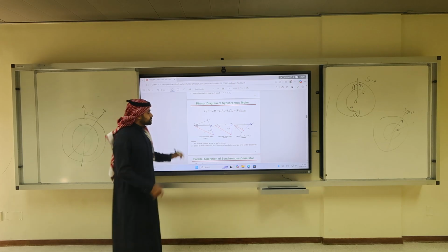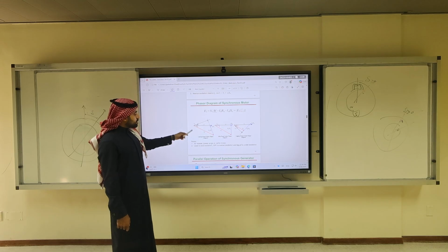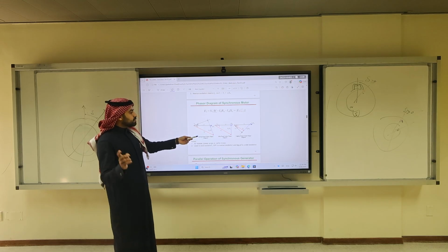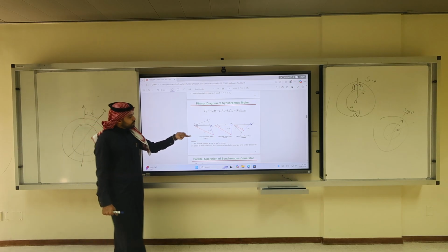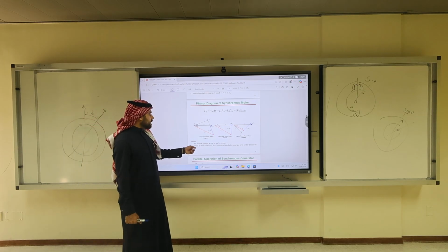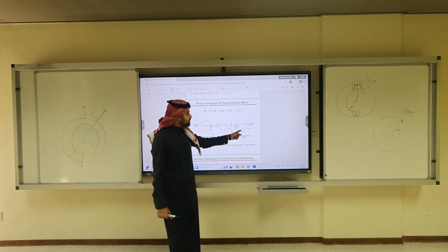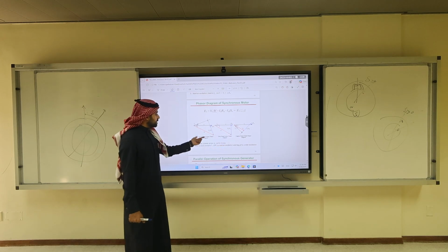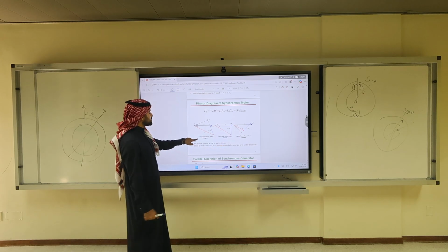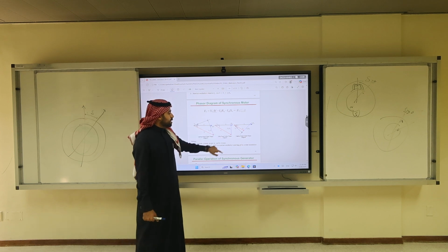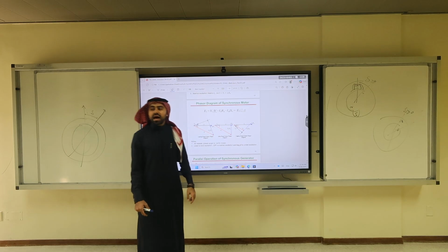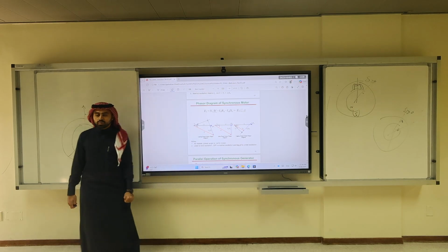Let's continue. For the leading power factor, we flip everything. So the leading power factor is overexcitation. Where is the leading? This is the leading. Here we have leading. Don't confuse yourself. This is leading. Overexcitation. Normal excitation. Lagging will become what? Underexcitation for the synchronous motor.